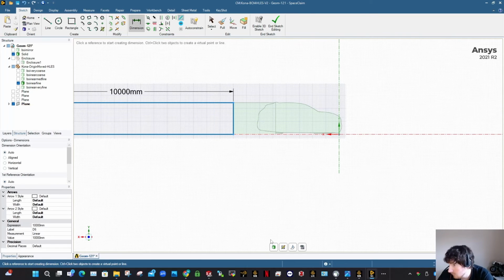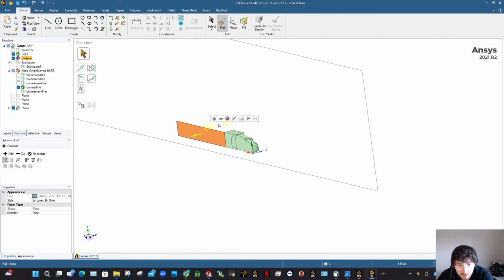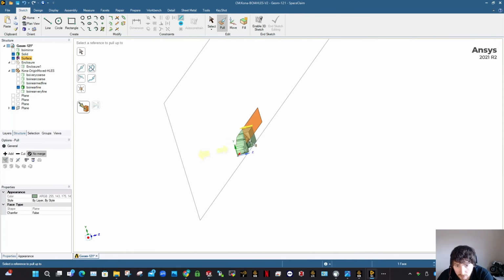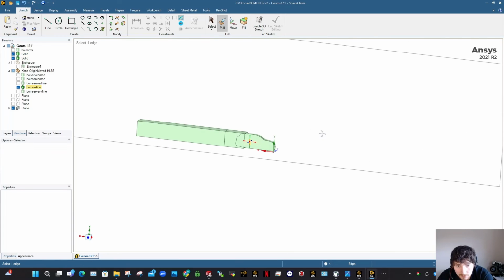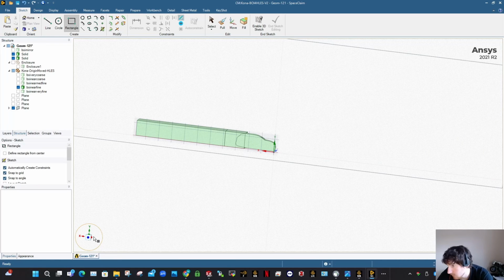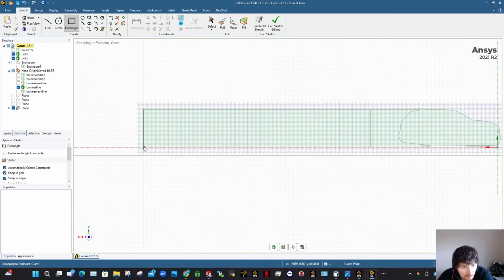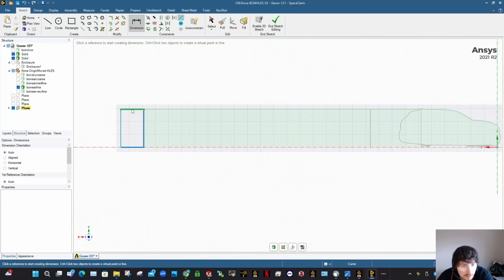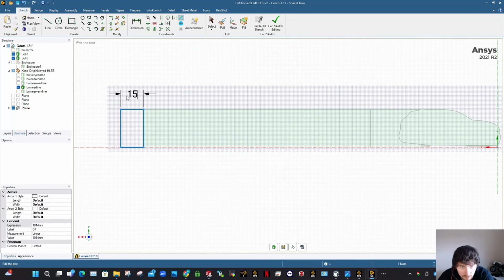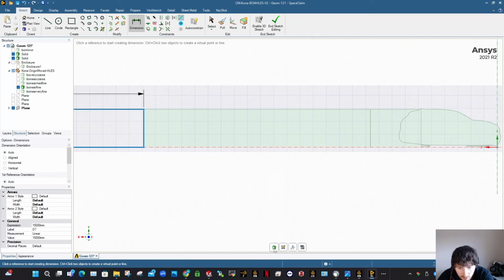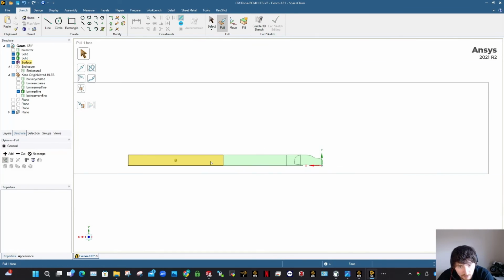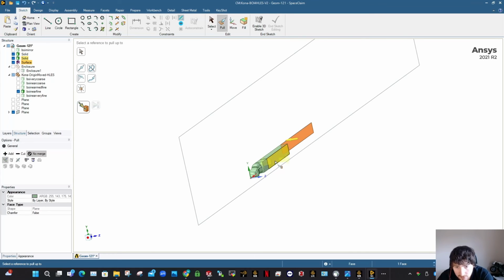Okay. And so same again. So what you do, no merge, and click up to that face there. So I'm going to do one now 15,000 behind this. So again, on the symmetry plane, grab the top there, dimension it 15,000. And again, you can come up with this as you want. So this is just something I know that works quite well for doing a hybrid LES simulation.